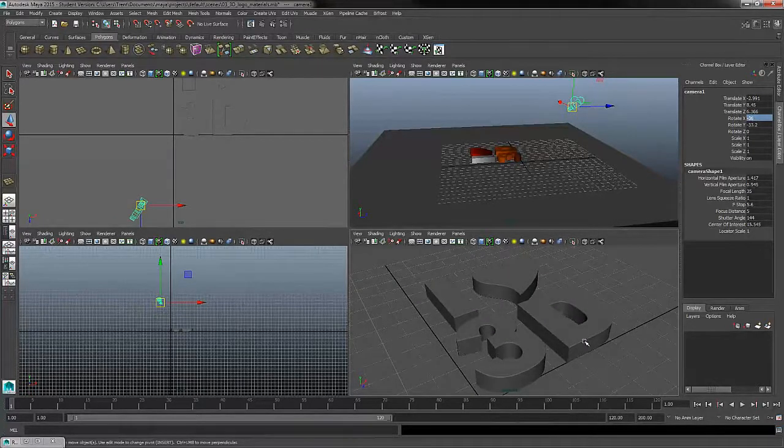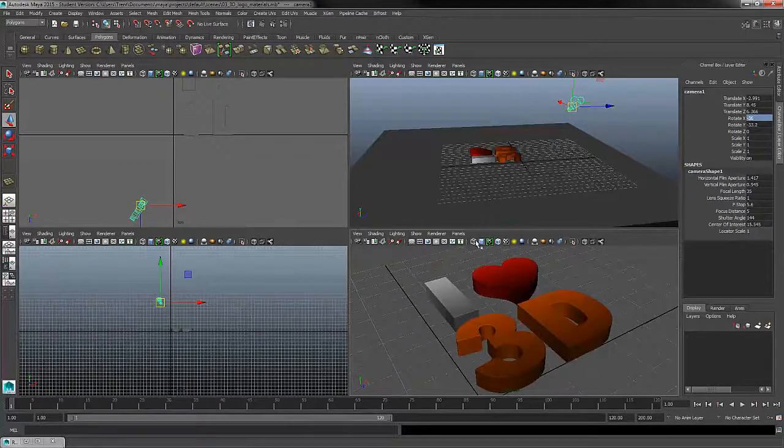Now again, just to recap from stage 2, we see our material textures in our perspective view, but we don't see those here in our camera view. So do you remember how to turn that back on? Well, just as review, we use our texture icon from our panel toolbar. So there we're able to see the textures that we've applied here in the view.